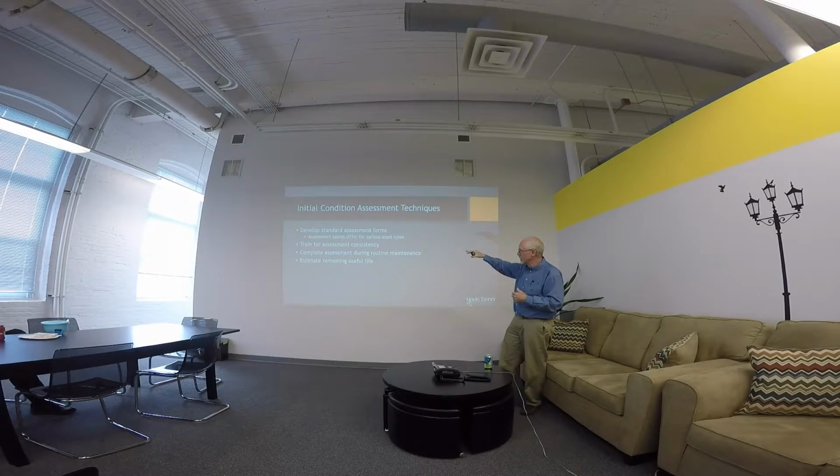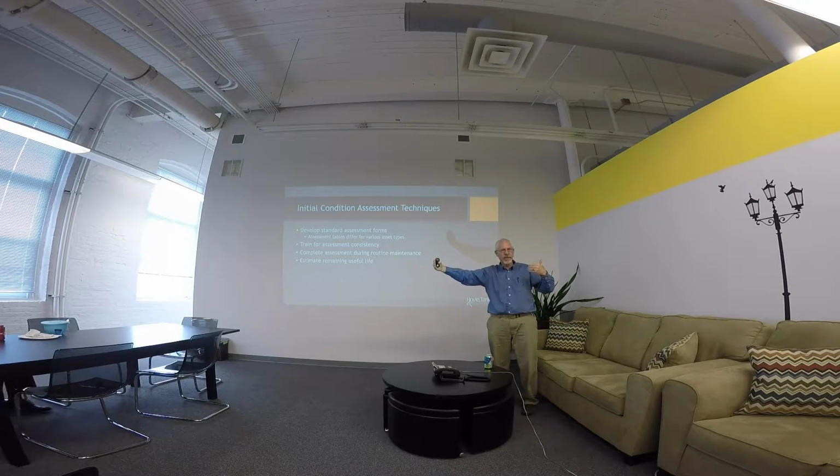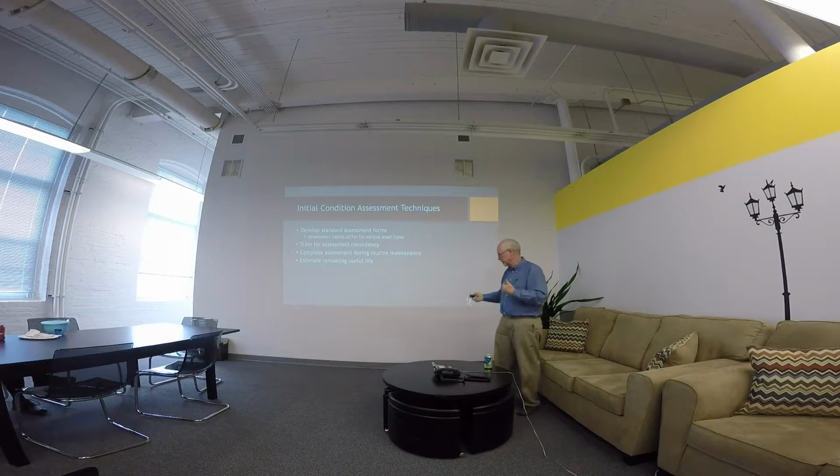And as you're doing the condition assessment, it allows you to do better estimating of life. A lot of times, when we talk about the accountant, we'll say, okay, the pipe life is 80 years. So that means 80 years to replace it. But through the assessment, what you're doing is all the pipes that were 80 years old really don't need to be replaced when they're 80. Some need to be replaced sooner, most of them probably later, through proper condition, looking at what maintenance needs to extend its life.